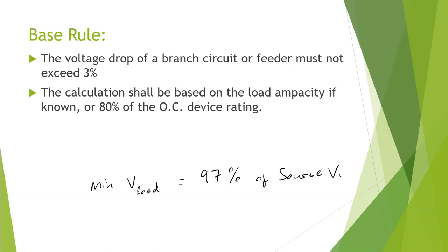So now when we move forward, we'll be using this maximum voltage drop allowable of 3% anytime a question does not have a specific limitation on voltage drop.